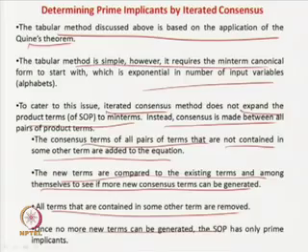There we actually do not require to do pairwise, because we have already separated the terms by no complement, single complement, two literals complemented, and so forth. Every term is compared: no complement with single literal complemented, and we keep on doing it. In a broad way, the expression is broken up into minterms, and every term is compared among themselves to find new terms. So obviously we get the prime implicants. But here the terms are not broken up, so we need some amount of proof that if we proceed with this procedure we discussed, it will work.